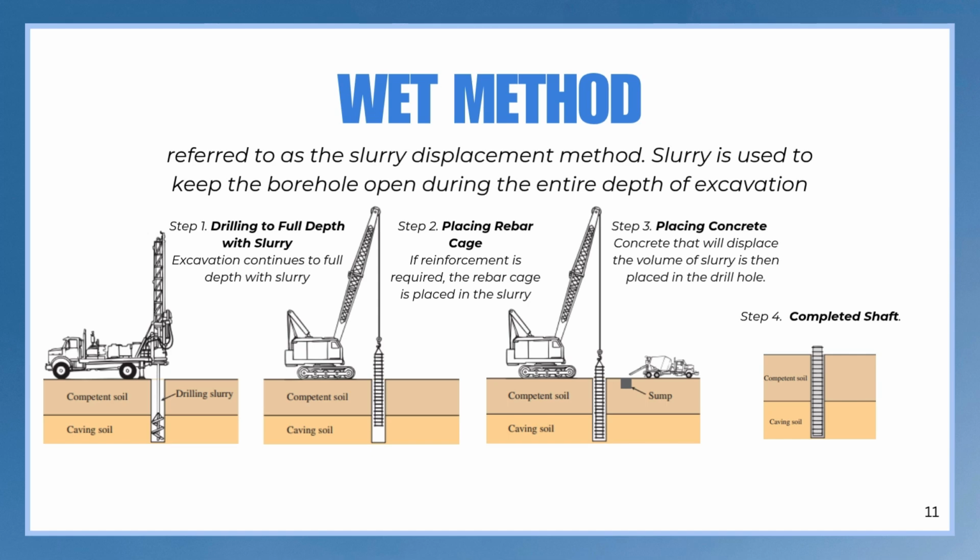Once the required depth is achieved, reinforcement is placed into the borehole. If structural support is needed, concrete is poured into the borehole. The concrete displaces the slurry as it rises, ensuring that the borehole is filled from the bottom up without contamination. Finally, a completed shaft is formed once the concrete fully replaces the slurry and sets, resulting in a stable and structurally sound foundation.